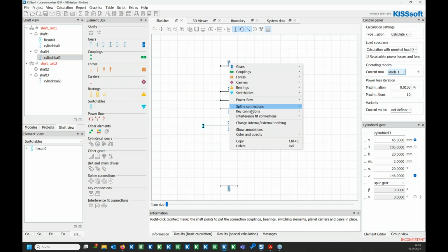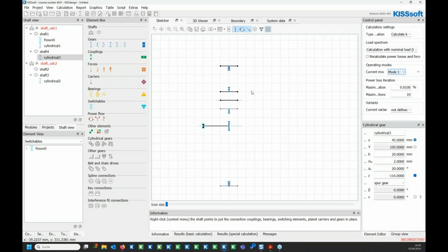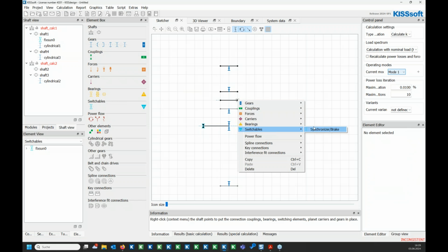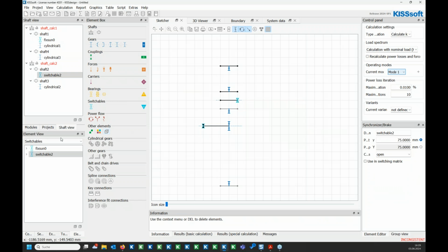And this gear is an internal gear here. Okay, so that's the standard planetary stage as known. What we must not forget is to set this pin directly closed, because we learned before that the pin shafts must be fixed. So that's fix in 0.